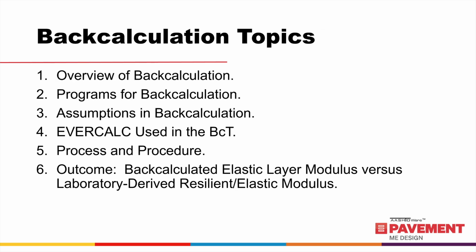6 topics will be covered in this session. The first is an overview of back calculation. The second is programs for back calculation. The third is the different assumptions in back calculation. The fourth includes EverCalc that is used in the BCT. The fifth is the process and procedure of back calculation. And the sixth is the outcome from the BCT, which is back-calculated elastic layer modulus versus the laboratory-derived resilient or